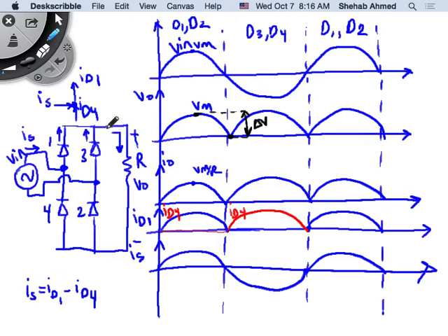I want to put the capacitor because the capacitor will charge from the supply, and if I've properly chosen my capacitor size, then it will maintain the level even though the supply is not feeding it, and it will maintain continuous current to the load. Remember that level analogy, level of water, bucket and load?